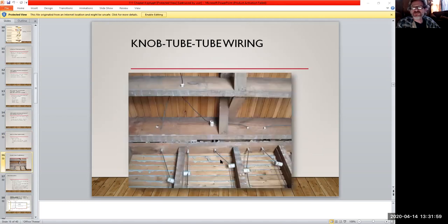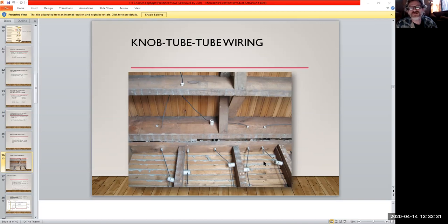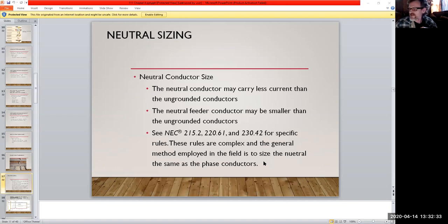Yeah, here you go. So yeah, look at this crap. So see those ceramic posts? I mean, granted, they're covered, if you will, but that little divide in there is exposed. That's exposed wiring. So little mice or crap over time, anything comes up in there, it would create a definite wire hazard, fire hazard. Stuff was awful. Hopefully you never. Oh, there's still some farmhouses out there with this. Believe it or not, with this crap still running through it.